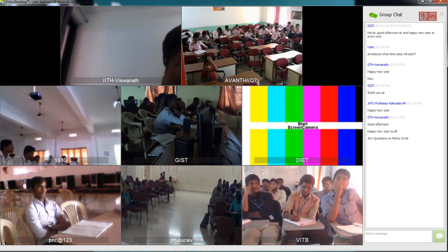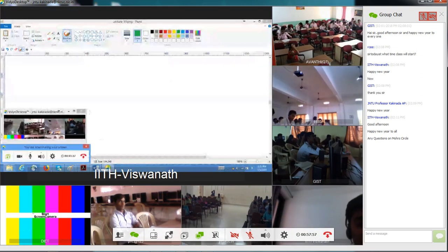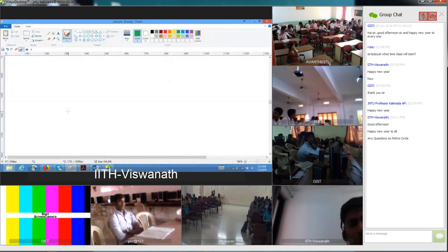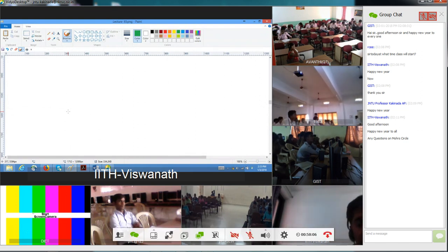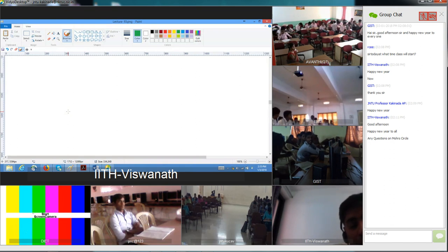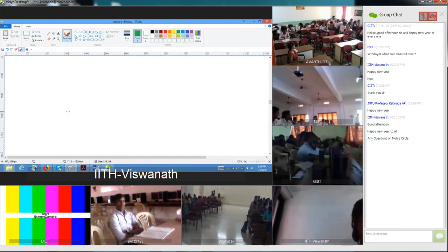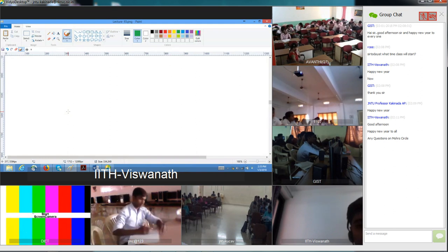Now, once we know how to handle a multi-axial stress state, note that a Mohr circle can only be drawn for a two-dimensional stress state. For the three-dimensional case, there is nothing like a Mohr circle. But for any given plane, if you cut a plane section, you can redraw the Mohr circle. So with this, the next topic we will do is theories of failure, and in the theory of failure, we'll make use of all the stress transformation that we have derived just now.